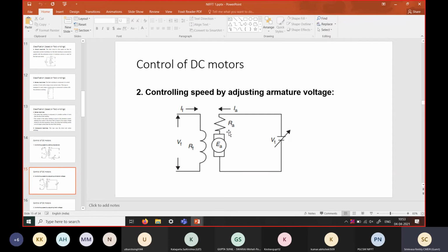Whenever any conductor is carrying current, it will have some resistance, defined as R = ρL/A, where ρ is the resistivity, L is the length of the conductor, and A is the cross-sectional area. Sometimes the windings, though they are in compact form, if you open the winding, the wire length will be quite huge.